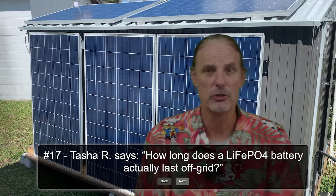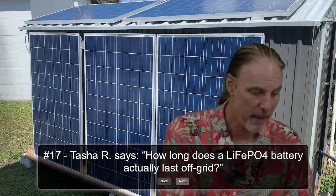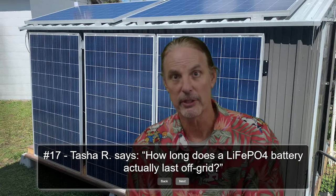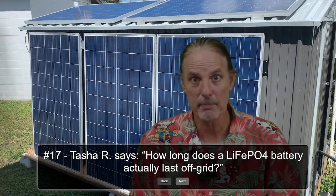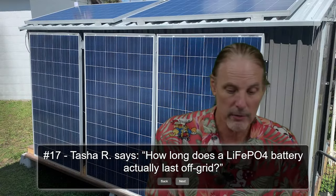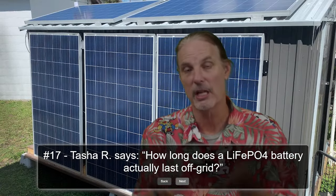Some manufacturers use 100%. So they say if I've got the battery going up and down to 50% twice, then that counts as a cycle. Some manufacturers use less than that. They say 80% depth of discharge. So if I go from 100% to 60% back up to 100% back down to 60%, that's 1 cycle.